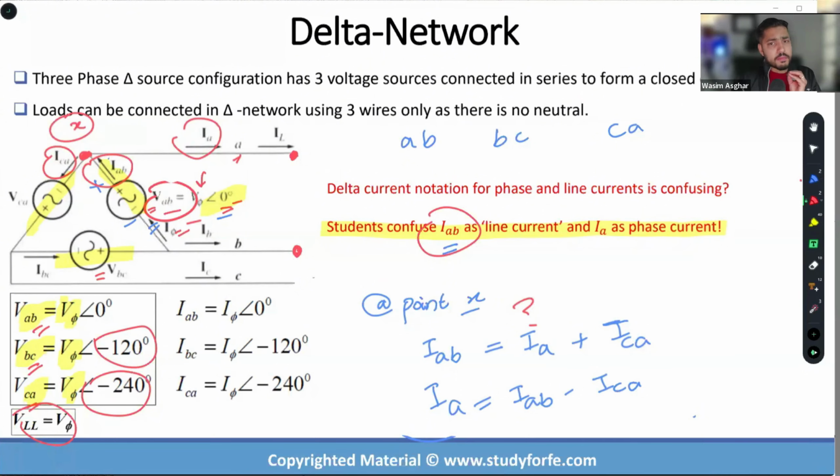Now, remember our voltage and current relationship, according to good old Ohm's law, is fairly simple. Voltage is directly proportional to current, or current is directly proportional to voltage. When you include an equality sign, you have to introduce a constant. If you're dealing with a purely real, resistive load, it just simply becomes R. If you're dealing with impedance that also contains a reactive component, then it's equal to Z. Let us assume that we are dealing with a simple real load.